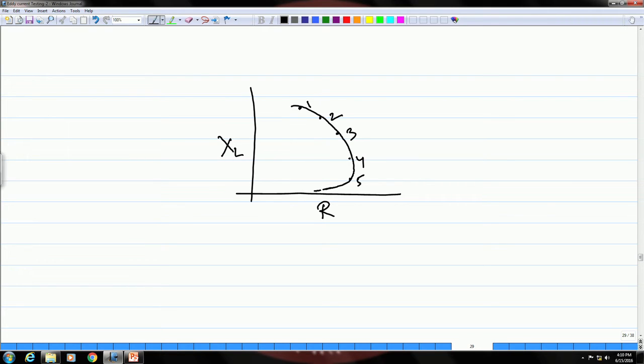Okay. So, that point at which the impedance Z does not vary any more with respect to the thickness, that particular thickness corresponds to a thickness which is greater than 3 delta, where delta is the standard depth of penetration as we have seen before. So, at this particular depth or thickness, you can call the sample a thick sample, beyond which the eddy currents will not be able to penetrate, because at such thickness, more than 3 delta, the magnetic field of the eddy current will be completely trapped by the thickness of the material. Okay. So, that is why this thickness with respect to eddy current is called a thick sample, beyond which you will not be able to penetrate the eddy currents. Okay. So, this is the effect of sample thickness.